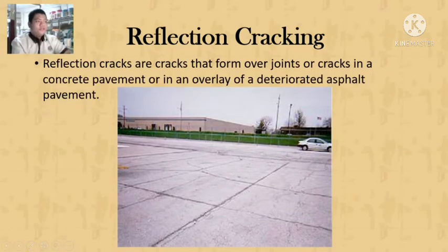Reflection cracking. Reflection cracks are cracks that form over joints or cracks in a concrete pavement or in an overlay of a deteriorated asphalt pavement. The cracks form because of the movement of the old pavement.